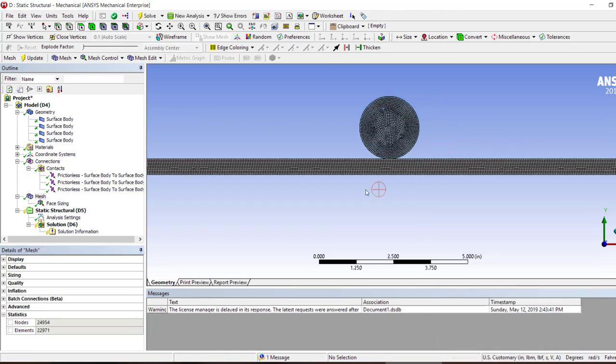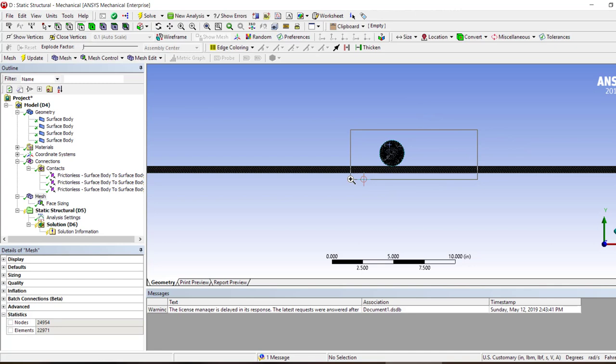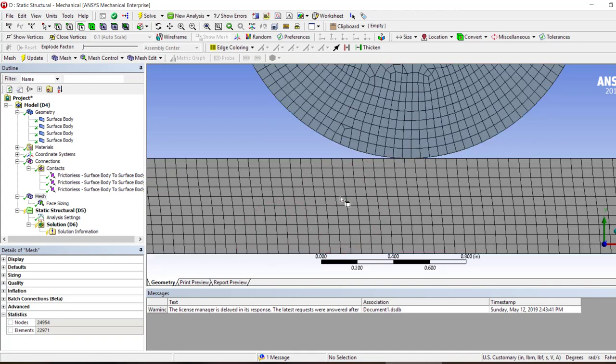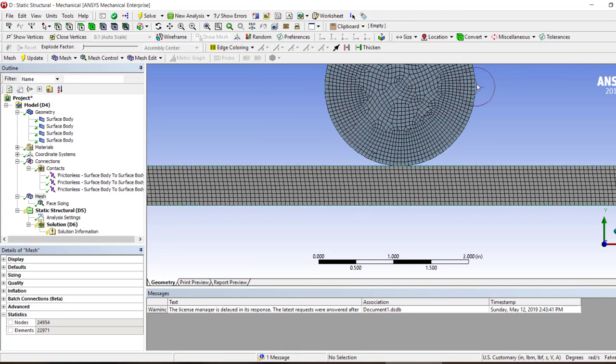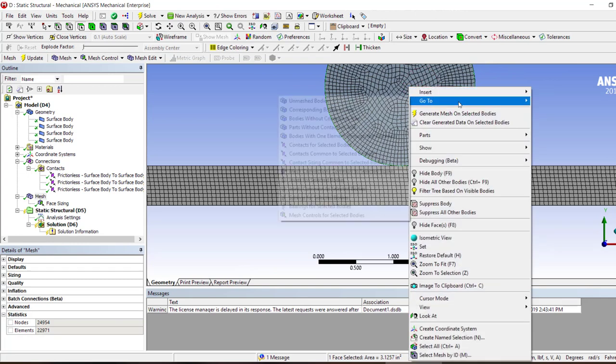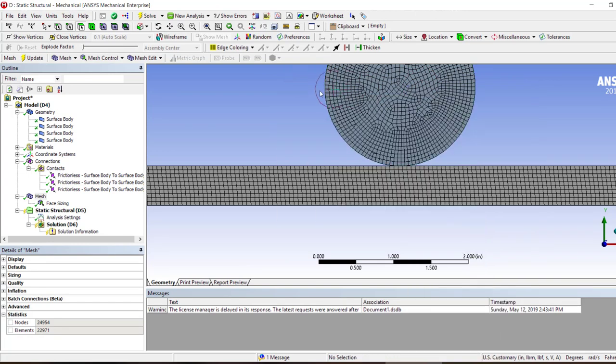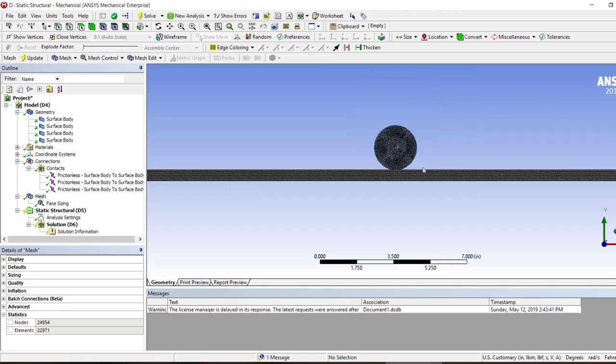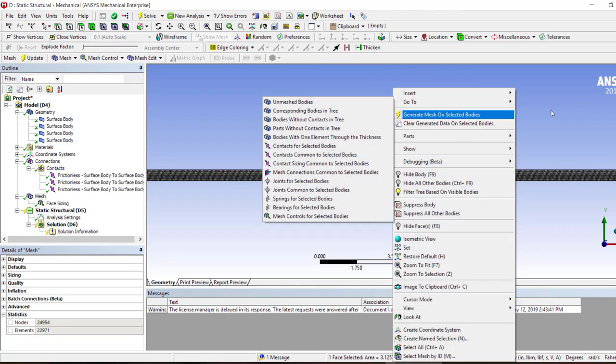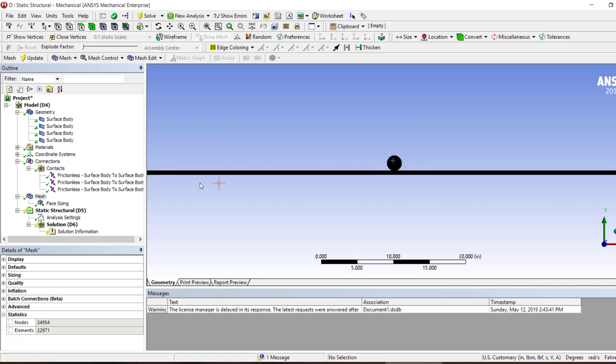And it took Ansys a little bit while to make this mesh, but it's too smooth. And we could have, you know, like half as much elements if we should just cut it in half. These pins were half as much because the only thing we need here would be this region, and they could have half as much elements and our problem would be a little bit simple and easier to solve.